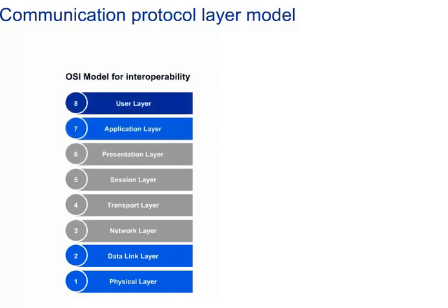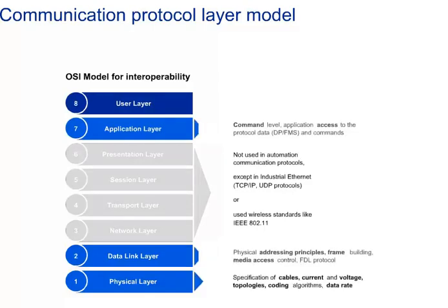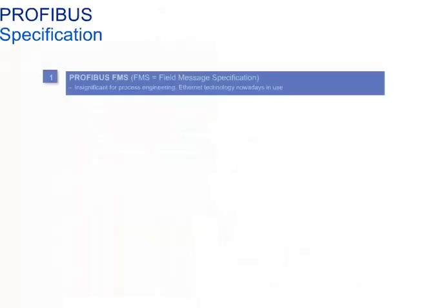Digital communication protocols have a standardized structure in accordance with the OSI layer model. OSI means Open Systems Interconnection Reference Model. Profibus also complies with the OSI layer model. However, Profibus only uses layers 1, 2, and 7 of the 7-layer OSI model. Layer 1 describes the bus physics. Layers 2 and 7 describe the protocol. For Profibus, there is another layer, layer 8, which describes the specific Profibus profiles. The individual layers are detailed in the following Profibus e-learning modules.